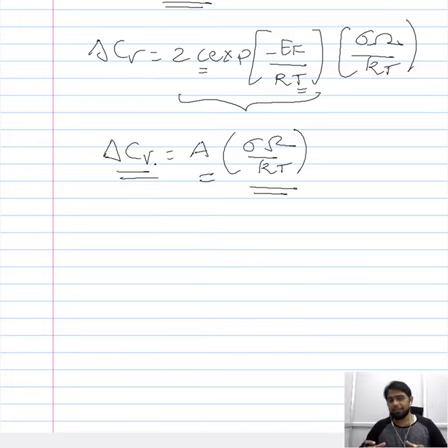that is the concentration of vacancies that is brought about by the stress. Now we can find the gradient of the concentration if we include the component of space into it. So far what we have considered is just the difference between the concentration of vacancy that is introduced by tensile stress and the concentration of vacancy that is introduced by the compressive stress. So we have found those expressions, we have taken the difference, and we have quantified the difference in the concentration of vacancies because of this difference in the loading condition.